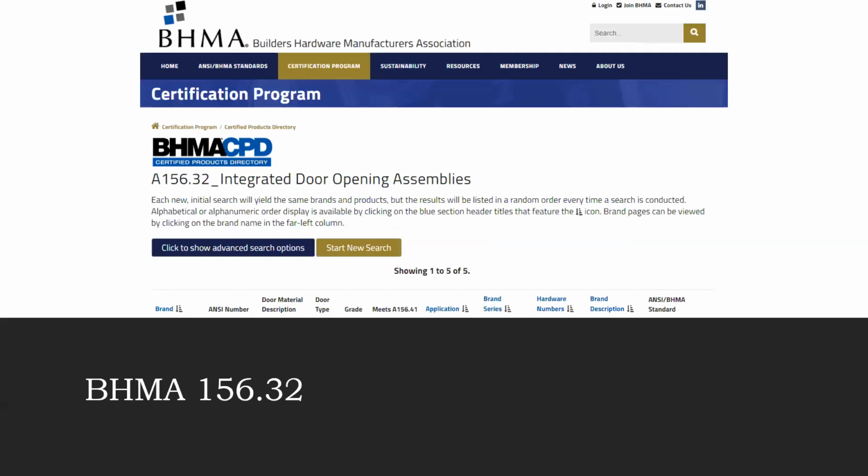Now, BHMA is the Builders Hardware Manufacturers Association, and they set the standards for performance that specifically impact builders' hardware. What's great about their website is you can go there, search any standard, and all companies that are certified to that standard will be listed. But the standard 156.32 is for integrated door opening assemblies. Now, limited products are certified to 156.32 because it is extremely difficult to pass. It takes months to pass this.